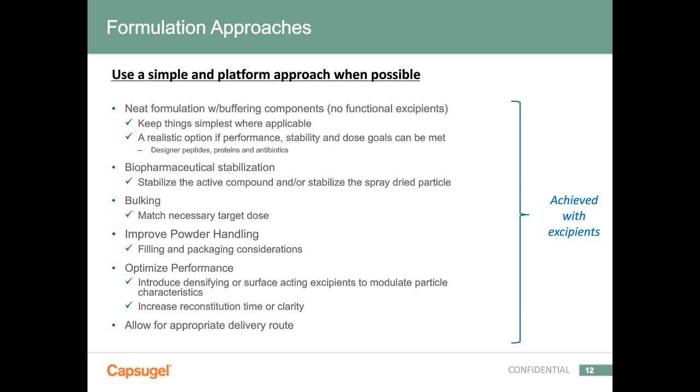And one thing I want to note as well is that macromolecules themselves during the spray drying process typically exhibit a slow diffusion step because we're using a water matrix. So when that happens, the protein itself goes and enriches the surface of the particle upon drying. And so it does lend itself to potential issues at the air-liquid interface when spray drying. So a lot of times we'll include excipients that will help protect the macromolecule itself away from the surface while drying. This is a distinctly different thing than lyophilization, when you're worried about cake formation.